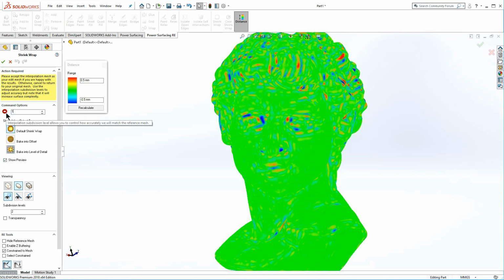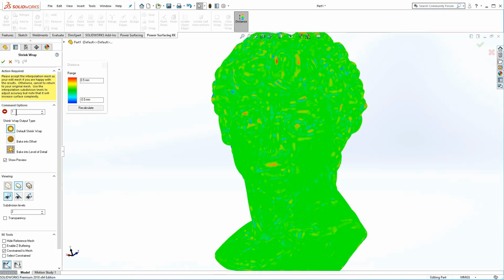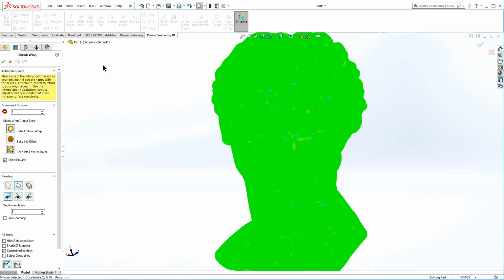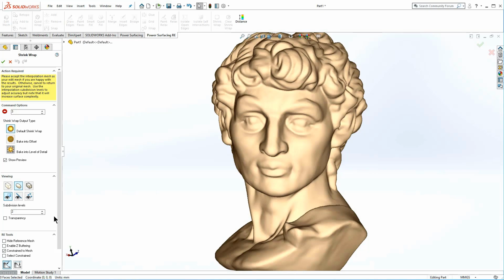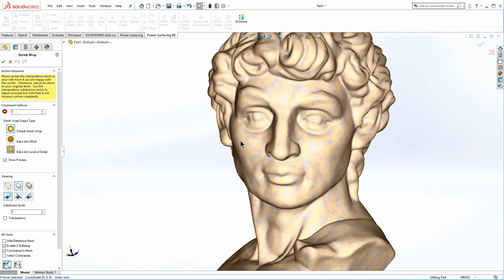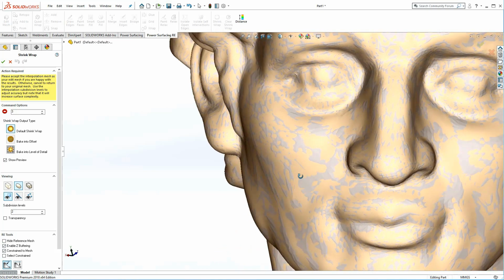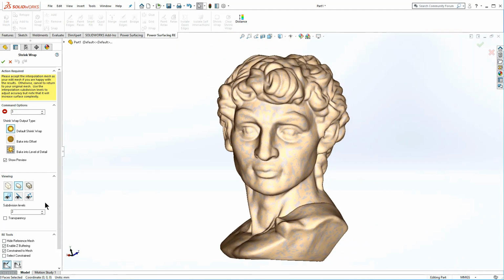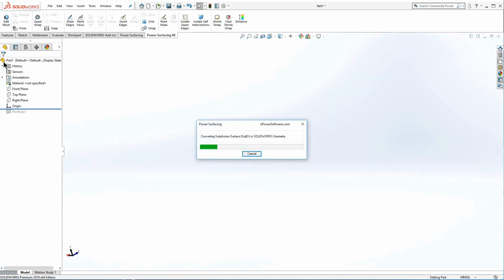At 1 extra subdivision level, there are only small areas at the edges of the range. At 2 levels, they are almost all gone. At 3 levels on this mesh, there is very little change. Shrink Wrap attempts to keep large areas of curvature smooth to counteract the roughness often found in the reference mesh. Turning off distance and enabling Z buffering illustrates the point. In this case, 1 level of Shrink Wrap is probably the best choice.